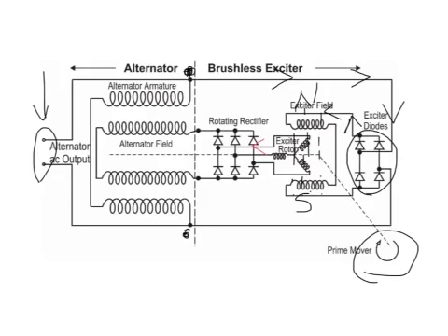And remember, this rotating rectifier is physically part of the machine. It's built right on the rotor itself. There are no brushes here whatsoever. So that AC current goes to our rotating rectifier, which is rectified by what kind of rectifier? Well, wouldn't you know it, we have a three-phase full wave rectifier, which will provide a nice or relatively clean DC output, which now means that current will flow to our alternator field.